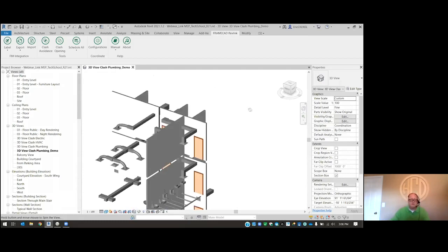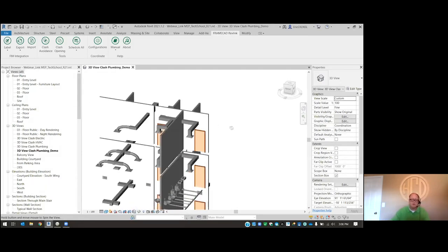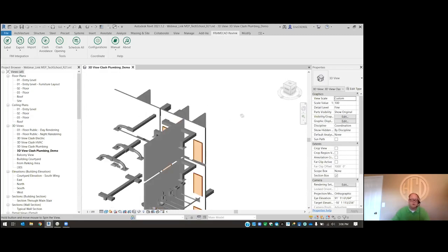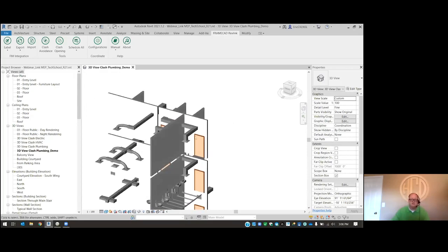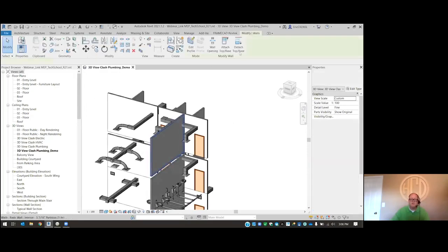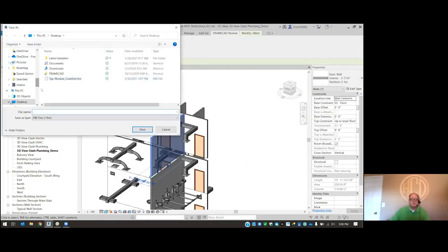The first tool that we'll take a look at is the multi-layer tool. What this tool is intended to do is allow the user to specifically select the layers of a wall they would like to export in the event that they have a multi-layer type configuration. So if I quickly grab this wall and we export it, we'll save this here as M layer 1.